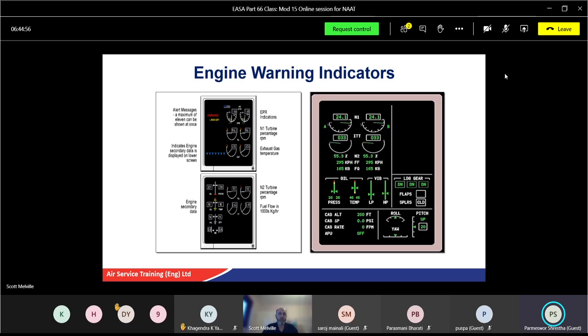The one for the gauges for indication, the ballast resistor. Good. That will give all indications reading the same temperature. So the ballast resistor is for balancing the indication for the pilot.